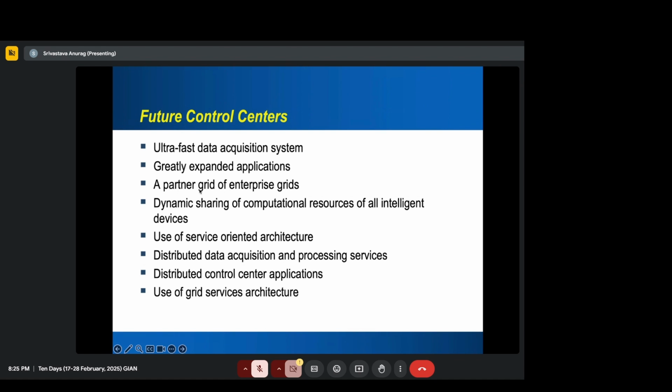In terms of the enterprise grid, how do we coordinate between multiple different grids working together, which is basically neighboring systems? Those control centers need to talk to each other to coordinate, right? One example is that if something goes wrong in one control area, every other control area will also see the impact, but they need to know that this challenge is happening in this control area, and how to solve it.